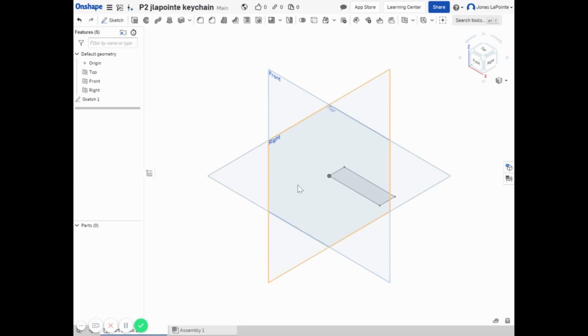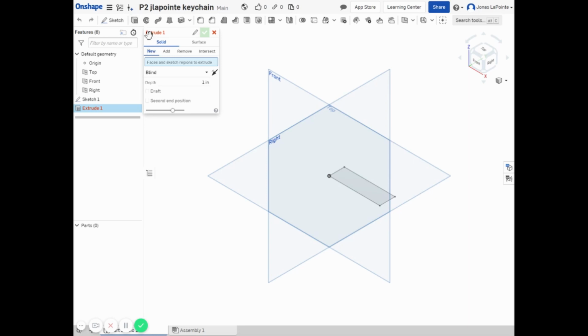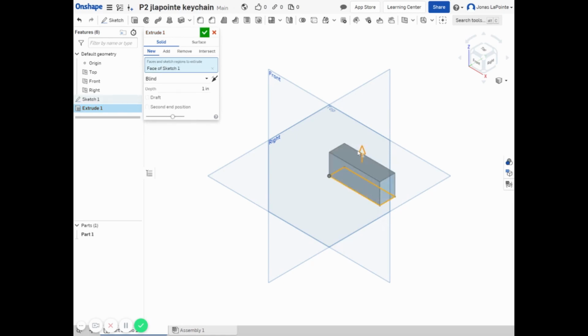This has now rotated our cube so it's facing with its back laying down on a flat surface like a table. And we have to give this shape some thickness by using the extrude tool, which is up here. Again, the extrude function is asking us which face we want to work with. We want to click on the top of our object. And that's way too big.